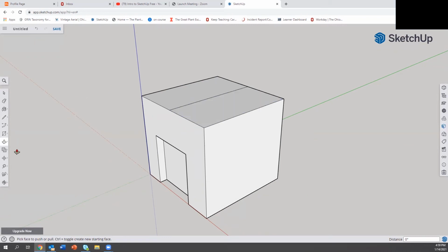Now what we're going to do is use the move tool. That's this button right here. It looks like a little cross. And we're going to grab the midpoint of just the line. See how it's separated out? See, I can grab anything there, and it wants to grab where I've just put it. And we are going to move that straight up.